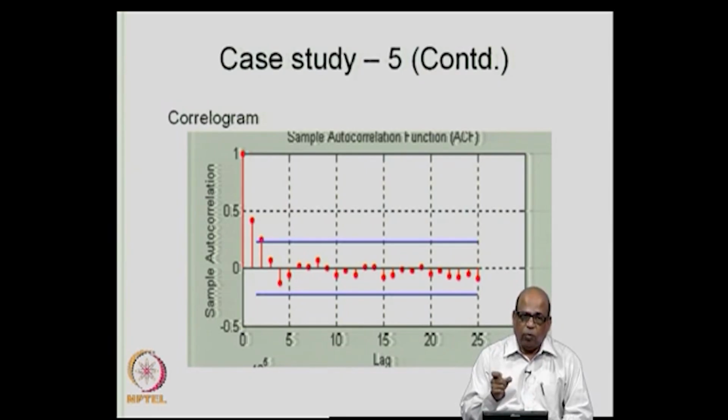Whereas, if you go down on time scales, let us say from annual you come to monthly rainfall, then from monthly you come to daily rainfall, etc., there are significant non-stationarities that will be present, which are not easily removed even if you do differencing. Typically on daily rainfall data, even if you do first order differencing, second order differencing, etc., the non-stationarities will still remain. So, when you want to apply the ARMA type of models, first you must make sure that you have transformed the original time series to another time series which is stationary. These models are only for stationary time series.